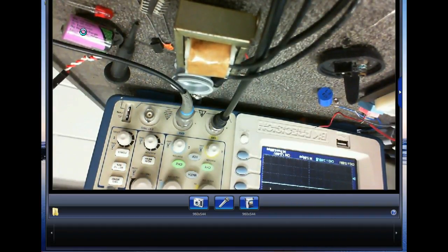So all we have to do: my regulator looks at the output, and if the output tries to go down, it increases the width of the pulses. If the output tries to go up, it decreases the width of the pulses, and that's the way these things work. That's why they're so good in cell phone chargers and stuff like that. They're so efficient. This one right here outputs 20 volts at 3.5 amps, and look at the size of it. It doesn't get real hot at all,